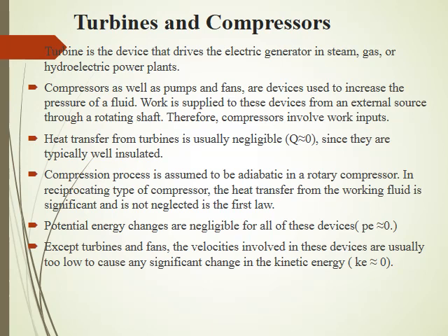Potential energy changes are negligible for all of these devices. Except for turbines and fans, the velocities involved in these devices are usually too low to cause any significant change in kinetic energy, which means you can neglect the change in kinetic energy, except for turbines and fans.